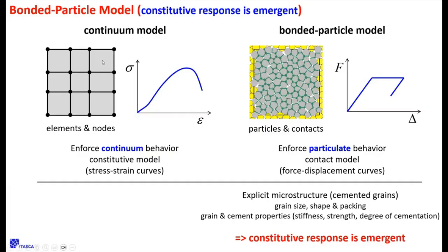And we call that a coupled model, and people do that, and we do that with PFC. And that way we can study in detail some of these complicated damage processes that occur at the excavation scale. We can study them by building microstructural models and embedding those in a bigger continuum so that we get the right boundary conditions.